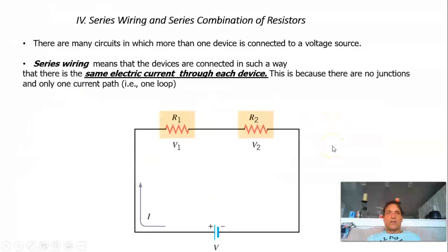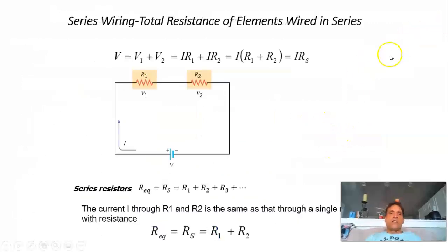So why do we do this? Usually we want to get the voltage drops across the resistors and everything. The first thing we need to do to get that is find the current. By calculating the total resistance, this equivalent resistance, we can divide the battery voltage, delta V battery, by the total resistance, and that gives us the current.